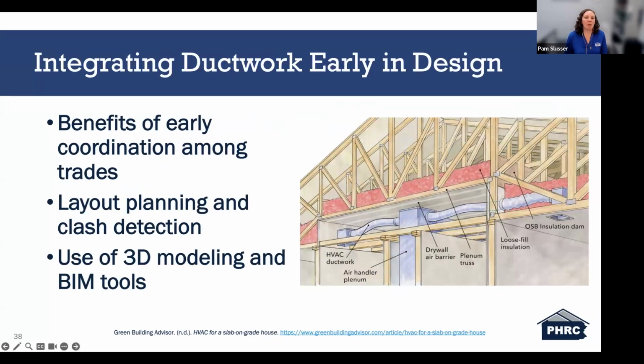So focusing on the importance of integrating ductwork early in the design process, one of the biggest benefits is improved coordination among the trades. When all your HVAC, framing, and design teams are aligned, it helps reduce conflicts in the field. Early layout planning also helps with clash detection. By identifying where ducts will run ahead of time, we can avoid issues with structural members, plumbing, or electrical systems that often can cause changes during the construction.